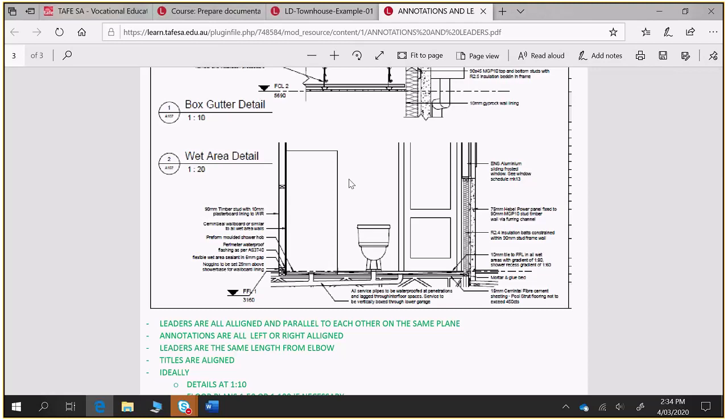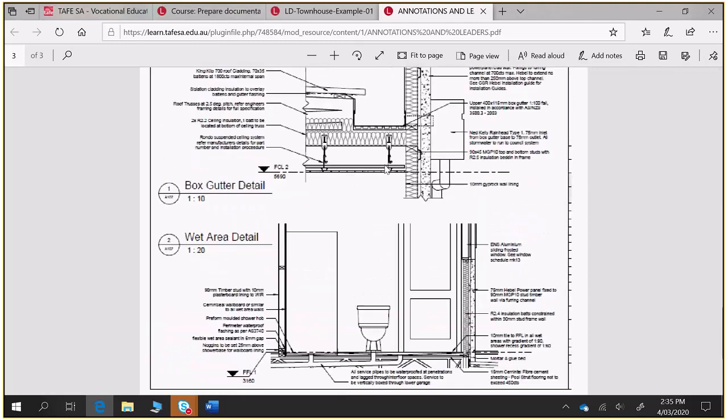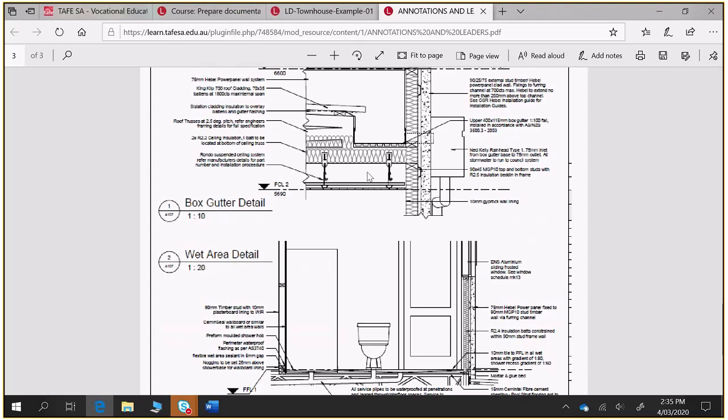And we've got the different textures that tell us very immediately that's concrete, that's insulation, that's a bit of timber. But in a bigger sense, seeing that grey stuff that is hanging off, obviously that's your suspended ceiling, and it looks like you've got another suspension for the ceiling lining, dropped down from that suspension. Those are things I'm just picking up from looking at that without any words. You've got a suspended ceiling and some sort of lining on it. So the top one has got some sort of load bearing capacity, I would suspect. Being able to say that from the drawing makes a huge difference.